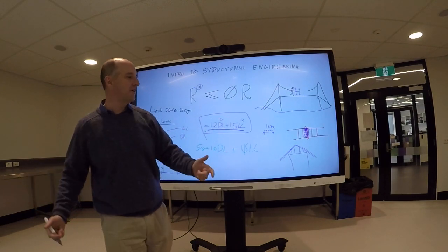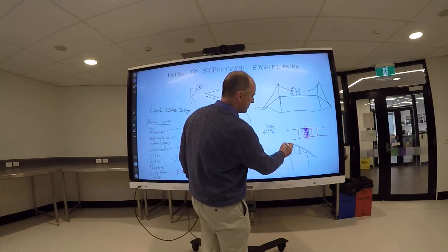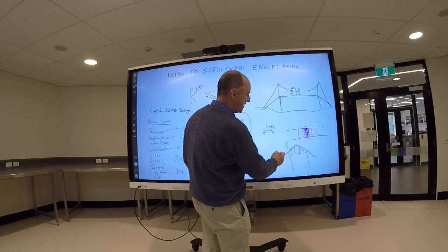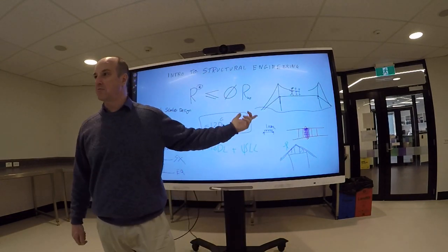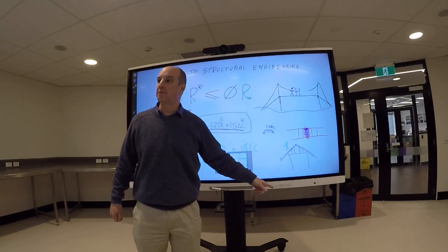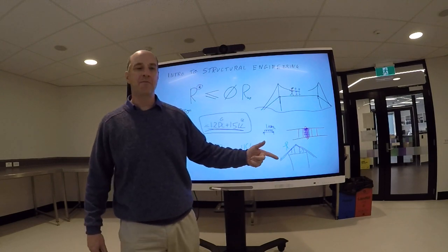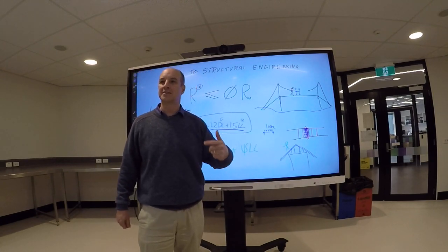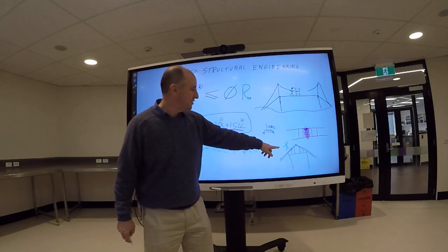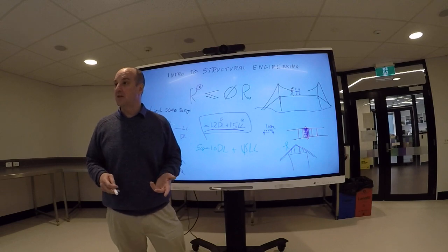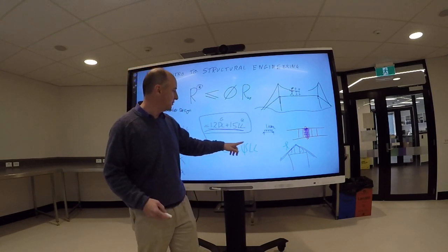What's the theory there? The theory is if you're designing this roof for the wind, the live load is actually a guy up here repairing the roof. When the sort of wind comes along that's going to blow the roof down, that guy's going to get off the roof before that, or get blown off the roof before that, okay? Same reason you don't have snow and wind loads together. The wind blows the snow away, okay? So those combinations, they're all in AS 1170. I'm happy to talk about them and help you through that, but that's basically what's going on here.